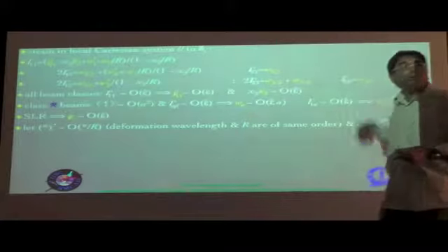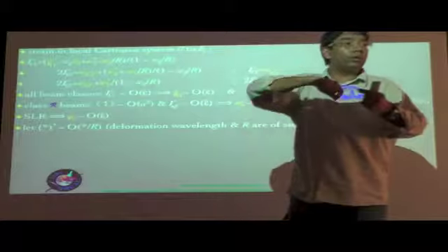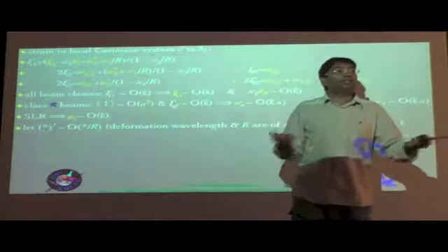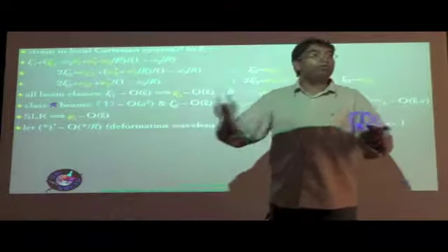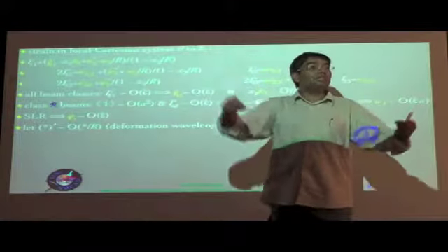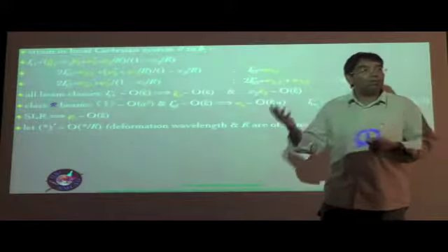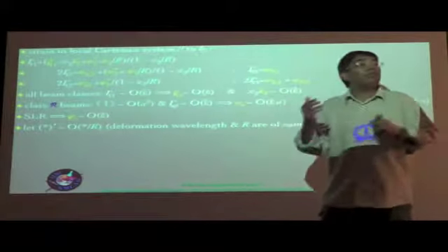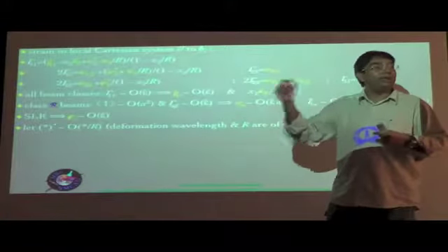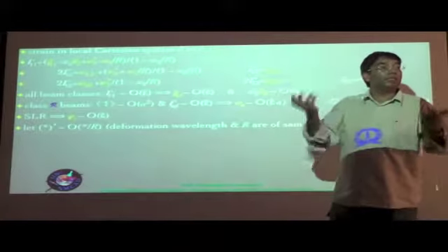for that matter even a full circle. You know that the circumference of a circle is 2 pi r, and 2 pi is about 6. So that is not an order of magnitude difference between L, the length of the beam, and the radius of curvature involved. That's what we are saying: R and L are of the same order of magnitude. If they were different, of course, you would have to take that into account and appropriately derive the theory according to the difference involved.